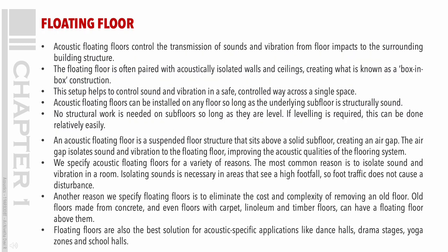Floating floor. Acoustic floating floors control the transmission of sounds and vibration from floor impacts to the surrounding building structure. The floating floor is often paired with acoustically isolated walls and ceilings, creating what is known as a box-in-box construction. This setup helps to control sound and vibration in a safe, controlled way across a single space.